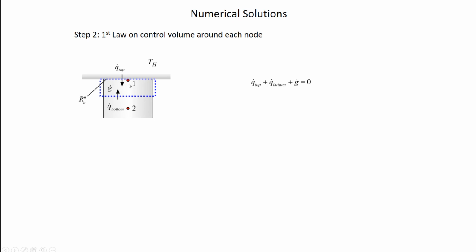I have to go back and now separately look at the nodes that are lying right on the edges of my computational domain. The reason is, again, these guys see something a little differently. If I look down from node 1, I do see a node 2, but if I look up, I don't see a node. I see the boundary conditions, the environment that my computational domain interfaces with. So this is where that comes into play.